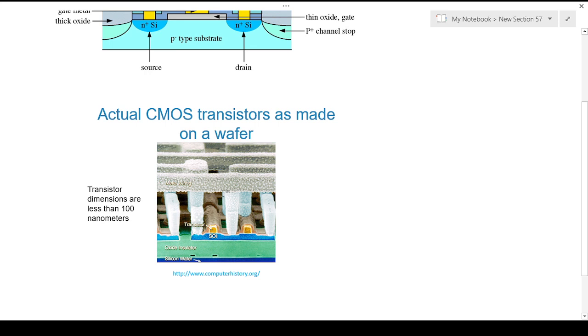So this is how the entire crystal structure will look. Also, this transistor will have a dimension of less than 100 nanometers. That's a very important point. The dimension is very small, and we need to work at this very small dimension in order to create this gate. This process of creating the transistor at a low dimension in IC chip making is very key, and in that key process, lithography is one of the processes involved in the patterning and preparation of ICs.